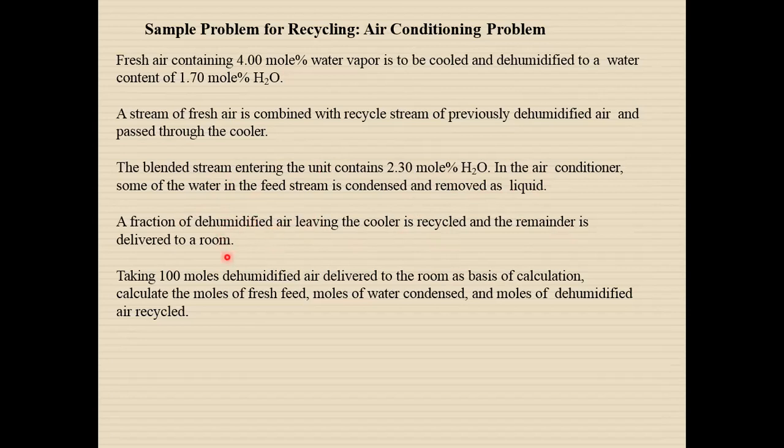So the air which was in wet phase, which contains the moisture, is dehumidified and is now utilized in the room for cooling and drying purposes. So take a basis of 100 moles of dehumidified air delivered to a room as the basis of calculation.